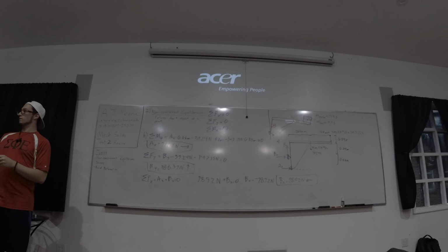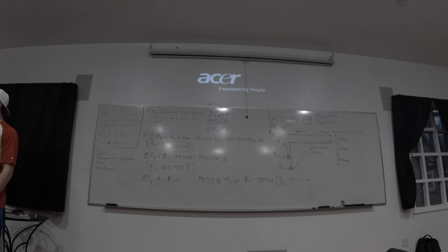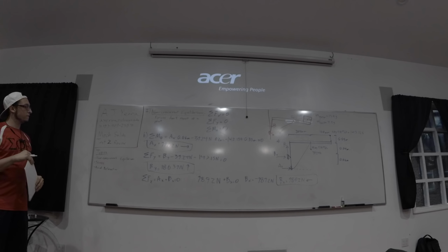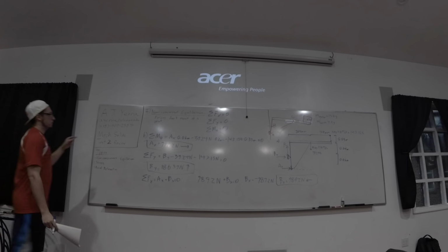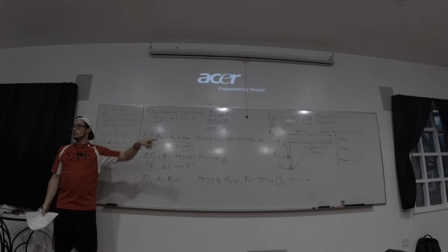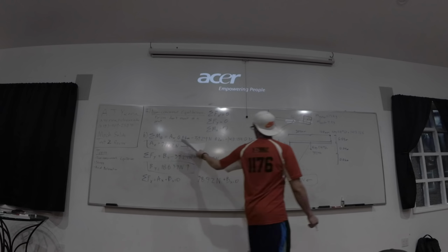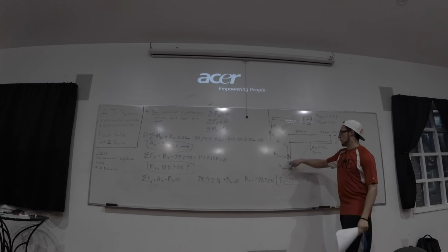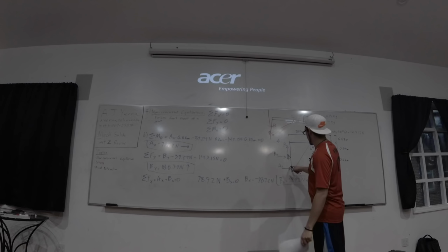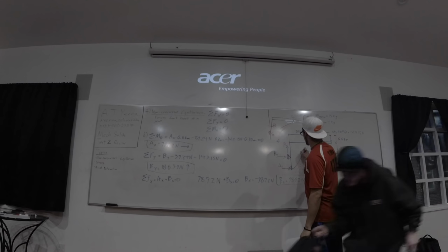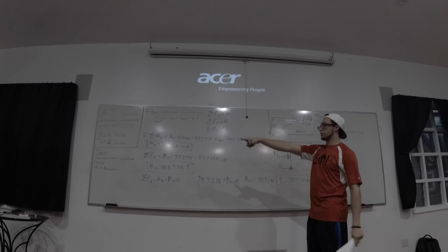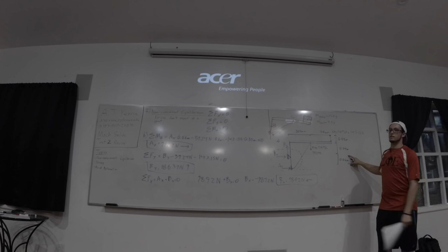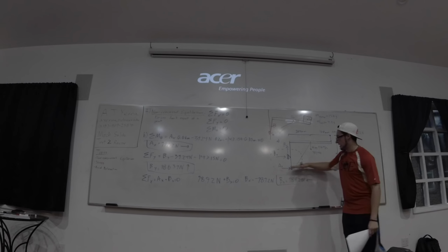Yes. You start with a moment of B. Ax, why is this 0.06? Say that again? Yes. You said x times 0.06. Oh, okay. So moment is equal to force times distance, right? So we're looking at this force vector about B. So we know it's positive because if you take Ax, it's going to go counterclockwise about B. So that's the sign convention for that. Ax is the magnitude of the force, and 0.06 meters is the distance between this line and B.